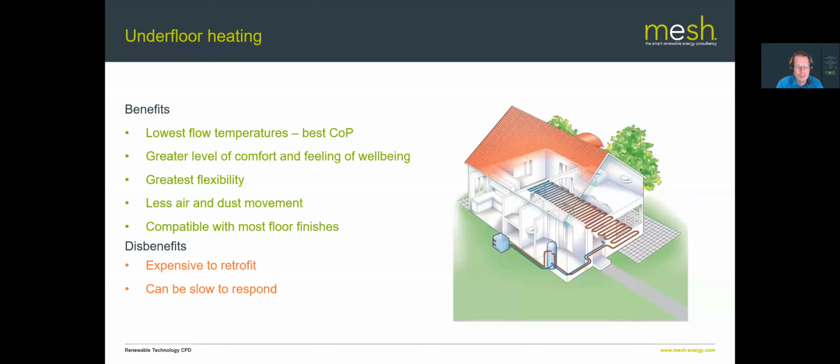But that's where that idea comes from, that, oh, I don't want underfloor in my bedroom because it will make the bedroom too hot. Well, no, we'll just offset when you're going to go to bed. Make sure you turn the heating down a good couple of hours before you go to bed, to allow the floor to start cooling down a little bit before you get into bed, and that will allow nice controllable room temperatures.